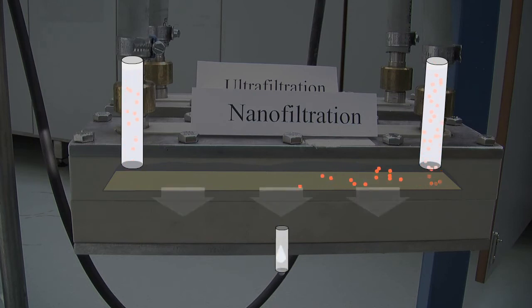Thus, rejected material tends to be carried with the reject water, enriching in the concentrate or being continuously removed from the filter module. One advantage of such implementation is that the flow is continuously flushing the membrane and hence retarding its fouling, that is, the accumulation of dissolved species at the membrane surface and in the pore.